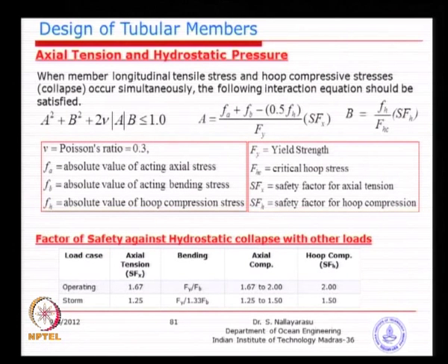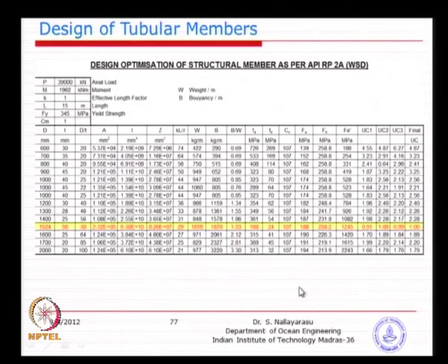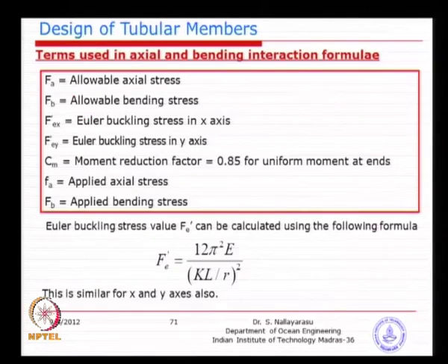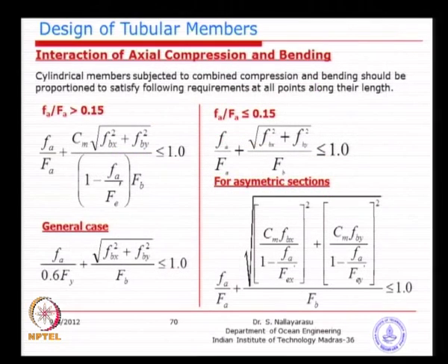So, slightly higher risk is taken for storm waves, while for the normal situation a reduced factor of safety is not allowed. Now, yesterday we were looking at the combinations. In these 4 groups of combinations we had axial stress combined with bending stress in all situations.